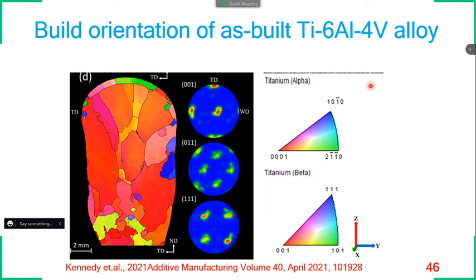For example, if a plant is oriented towards the sunlight, we can say it is perpendicular. But if a grain is oriented, in what way can we name it? We can do that by giving it a particular texture, in which this grain is oriented. So which direction is the grain oriented in? That is what the idea of EBSD, electron backscattered diffraction, is all about.